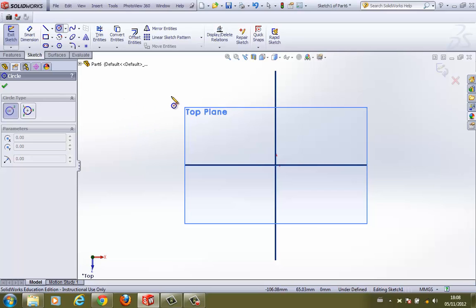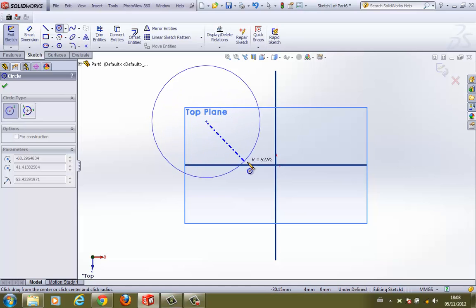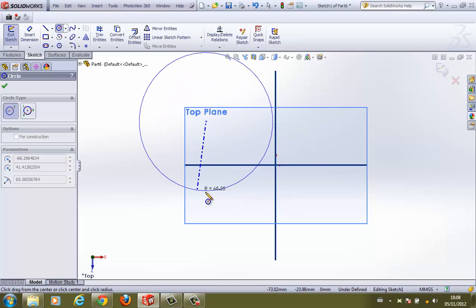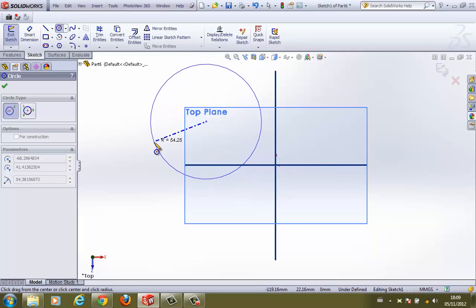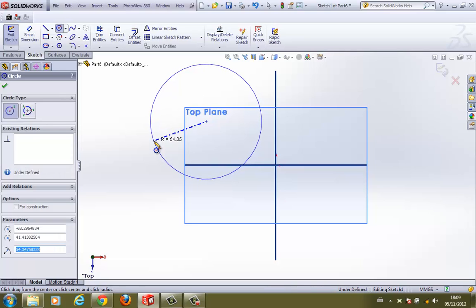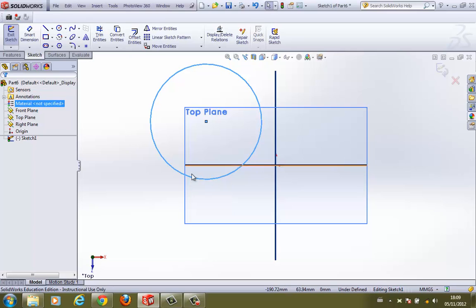If I were to just draw a circle, let's just say I'm not going to snap anywhere, and you wouldn't obviously know what snaps are because we haven't talked about it yet. I can quite simply click to locate the center point of the circle, and I can drag the cursor out. So I can drag it over here or here, anywhere will do. If you just drag it out, basically you're defining the radius. You're spanning out the radius of the circle. And if I were to click again, that's like specifying how big you wanted the circle, what the radius of that is. And if you're happy with how the circle looks, I am happy with this circle, I'm going to green tick, so commit to that.